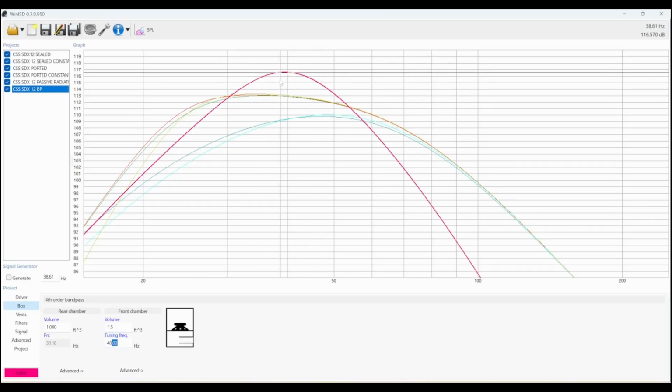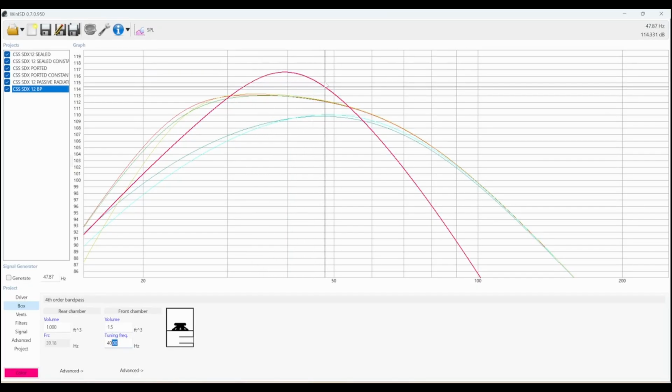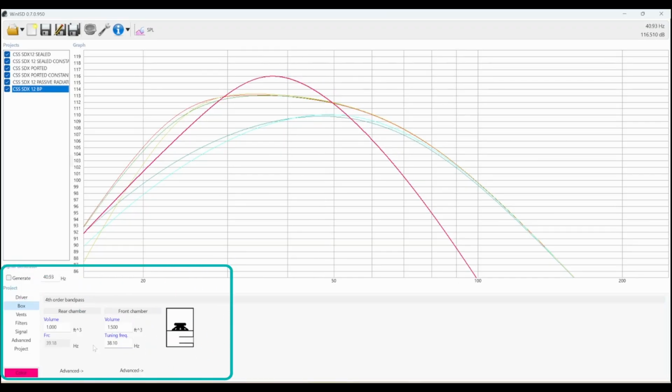This isn't very good for sound quality, although you could tune it out with EQ, but you can use this to your advantage in a bandpass box by optimizing the response. The trick is to figure out that sweet spot, making one small change at a time to figure out what you can give up and what you have to stick with. But a bandpass box typically will not sound as clean as a ported box, even if you get the responses pretty close to each other, and I'll show you why.